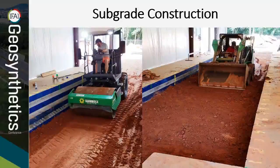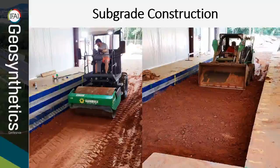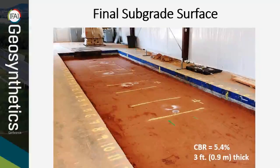These two photos show the grading and compaction of the subgrade. The subgrade was a local fill material typical of South Carolina. It was constructed at its natural water content. The final depth of the subgrade was 0.9 meters and had a CBR strength of approximately 5.4% based on dynamic cone penetrometer, or DCP tests.